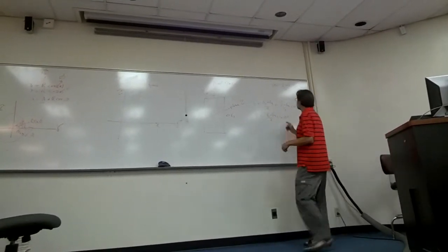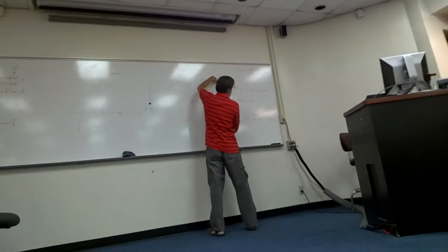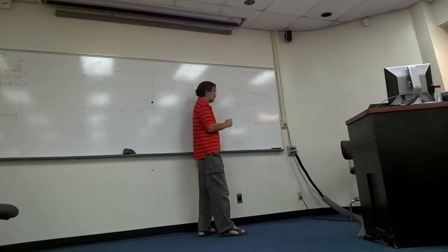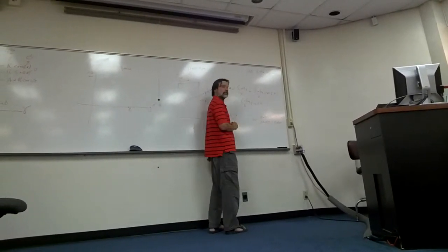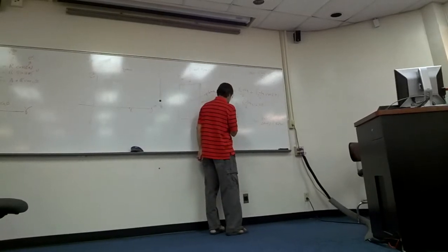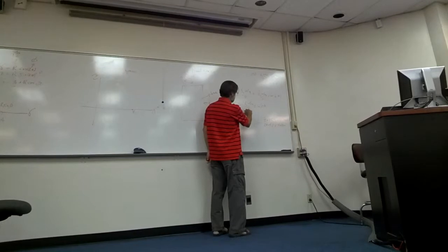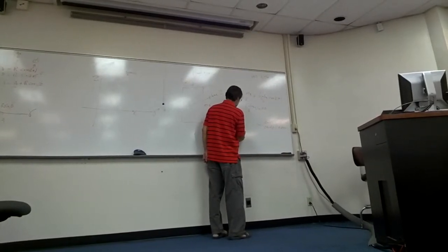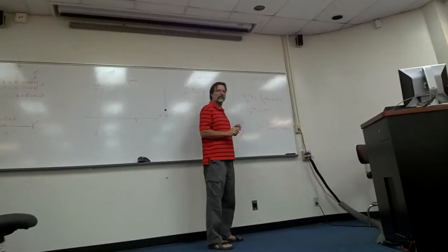Okay, let's do that calculation. So sigma equals, that's 0, right? That's sigma 1 plus sigma 3 over 2. And tau equals that, sigma 1 minus sigma 3 over 2. So both of these have value now.